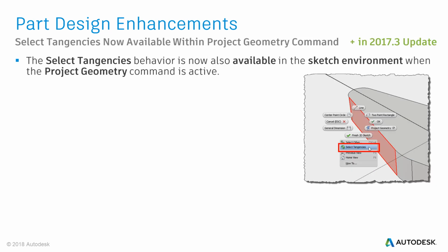On top, in the Inventor 2017.3 update, the Select Tangency behavior is now also available in the sketch environment when the Project Geometry command is active. Before 2017.3, Select Tangencies was only available in the part and assembly environment.